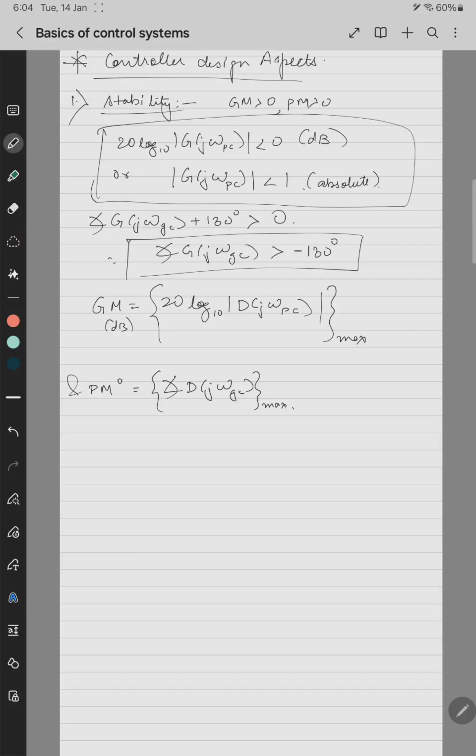So we'll always prefer a PI controller and assume we are using one. So there is no need to specially analyze steady state error. We'll directly go to the second point, transients, and for a second order plant, that is rise time, settling time, and peak overshoot.